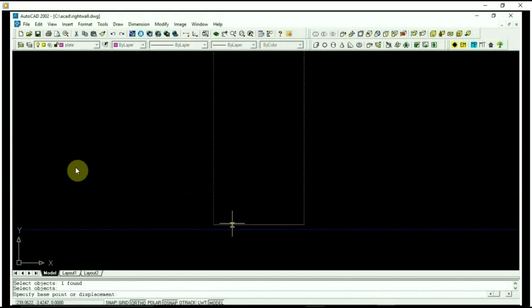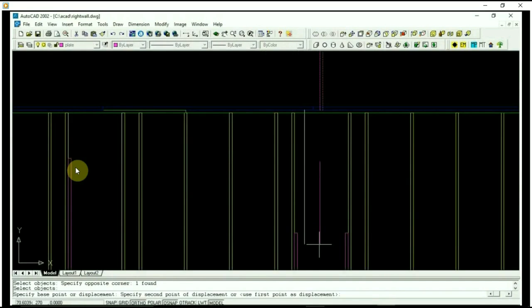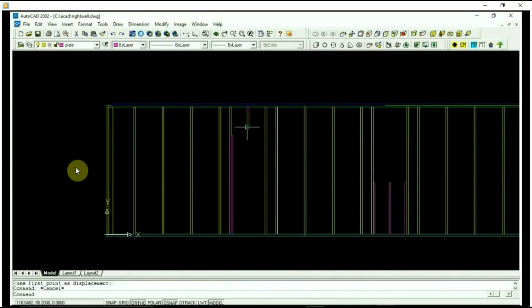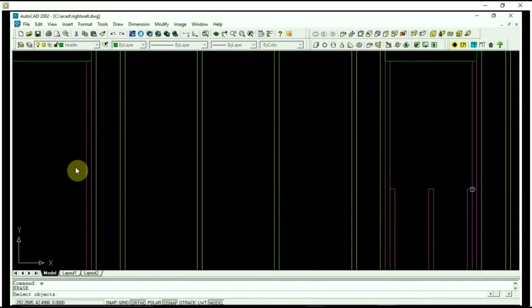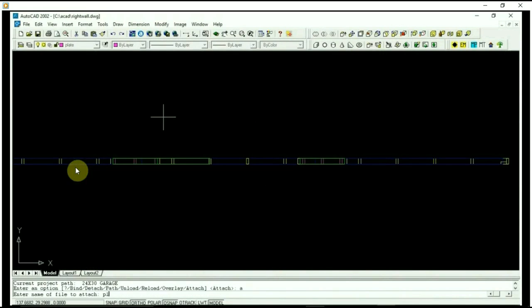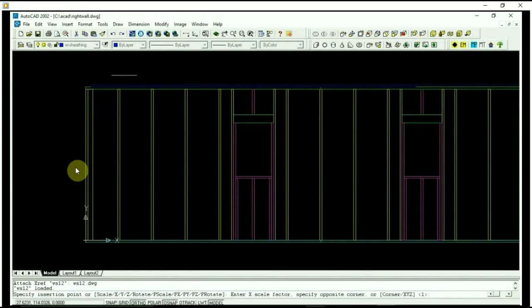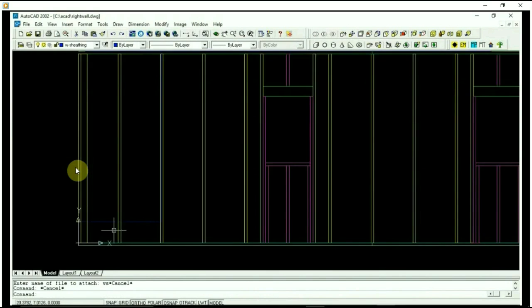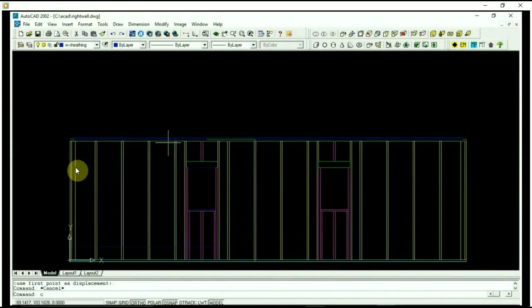There have been some improvements. AutoCAD 2000 changed the plotting so that you could send just your line weights to somebody and they weren't integrated with your plotter. Before that, line weights were assigned to a plotter driver, and I might have several clients I worked for, so we'd have one plotter, but I would have five different plotter setups depending on the line weights. Then when AutoCAD 2000 came out, you could just pick the plotter, one plotter name, and then pick the CTB file that you wanted, which was the line weight definition. So it was more streamlined there. AutoCAD 2006 came out with dynamic blocks, which are kind of a precursor to Inventor and what it does.